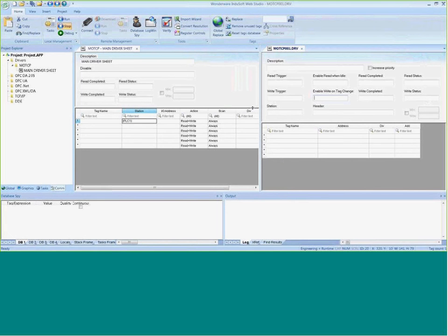So unlike a lot of machine control where you want it happening at a millisecond type rate, there's a 24-hour scan, right? Another good example of this is I went to a customer that had about 100 machines running InduSoft, and everything was running great on all but one machine, and I had to go visit them because they were getting a huge scan time. Well, it turns out that every cycle of the machine, they were reading in an array of 1,000 different part numbers that were 1,000 characters long, and that was slowing things down. So I said, how often do you actually change these part numbers? He said, we change them just on Friday, once a week.